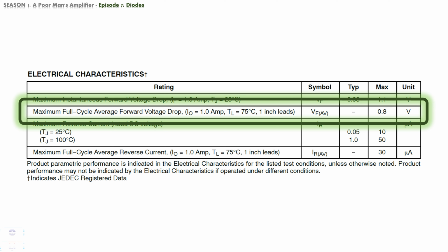Now, this is the parameter we have been looking for. We want to know what the voltage drop across the diode in our circuit is, so that we can calculate the value of resistor R, so that we could have a continuous current of 20 milliamperes flowing through our circuit. This specific parameter is obtained at very unique laboratory conditions listed in parentheses. Let's look at them closely.